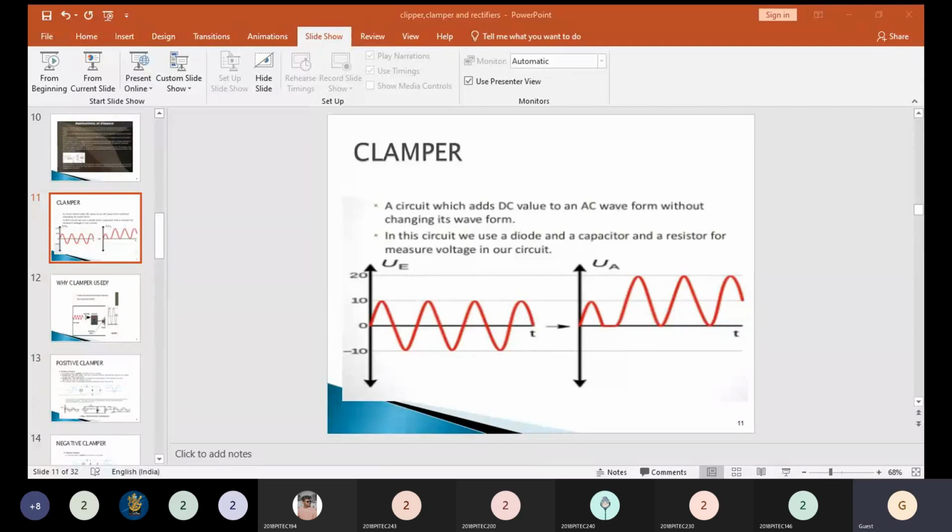So we can replace Vm divided by R with Im, giving I equal to Im sin omega t. So Im is equal to Vm divided by RF plus RL. Here I is equal to V by R, and both resistors are connected in a series combination, so the resistors are added.